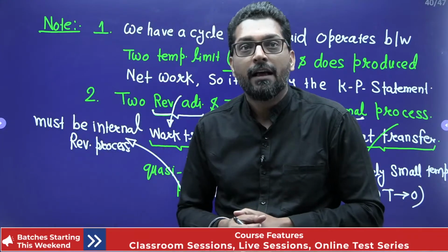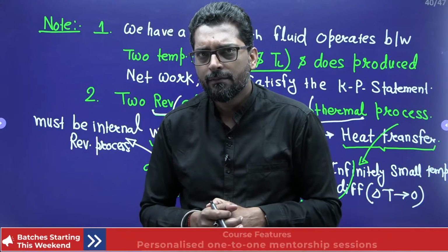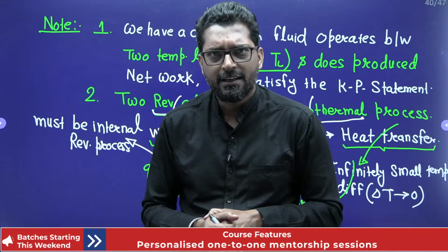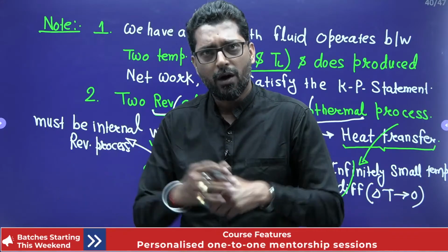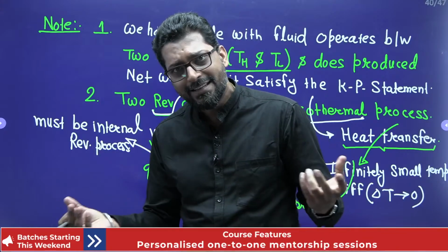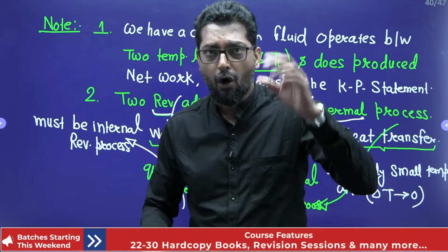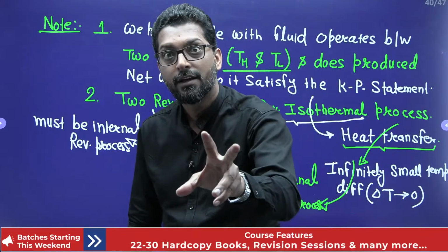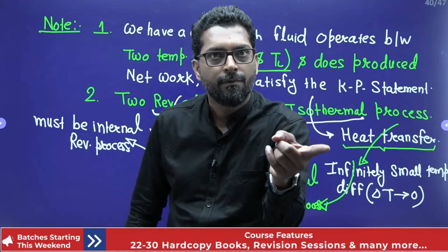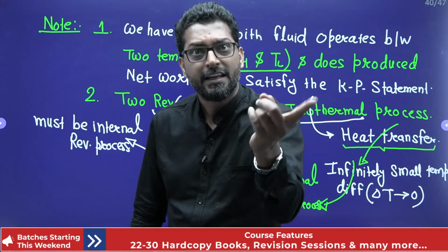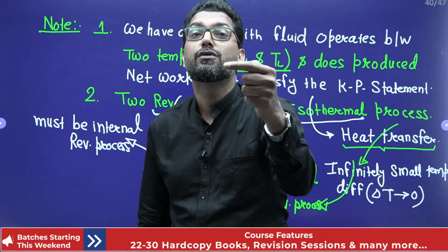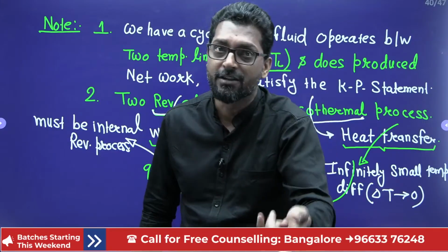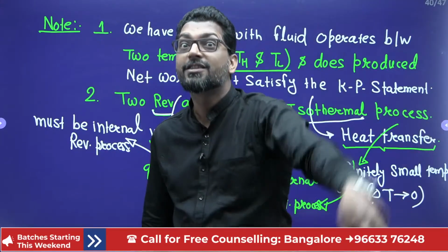Rankine cycle, it is a reversible cycle. Otto cycle, reversible cycle. Diesel cycle works on a reversible cycle. Dual cycle works on a reversible cycle. So all the thermodynamic cycles you design, except vapor compression. In that vapor compression, there is one process known as throttling, and throttling is a highly irreversible process. So all the reversibility vanishes.